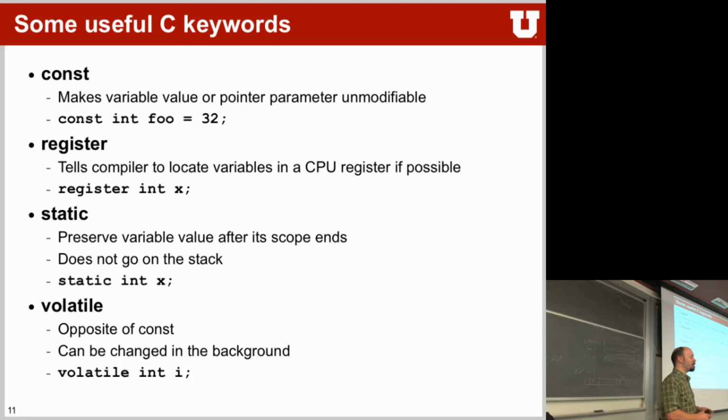So if you declare something as const, it will go into the data section of your linker script. And the data section is usually in ROM, which is a memory location. And what would happen is, yes, it would eventually get read from that memory location into a register to do operations on. But it's in ROM and not in RAM, because you can only read from it. You will never be able to write back into it unless you do a more complicated operation on the flash memory.